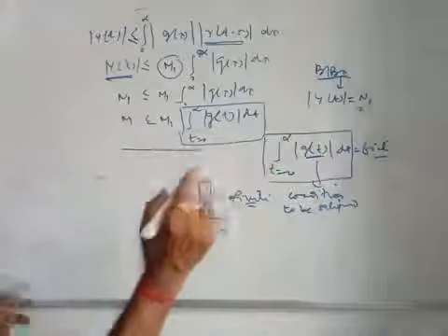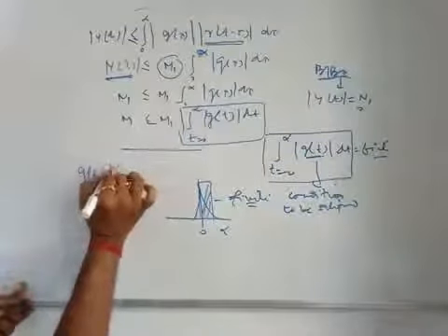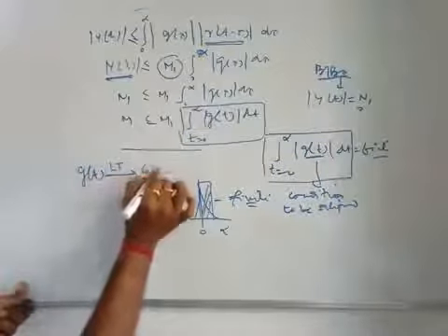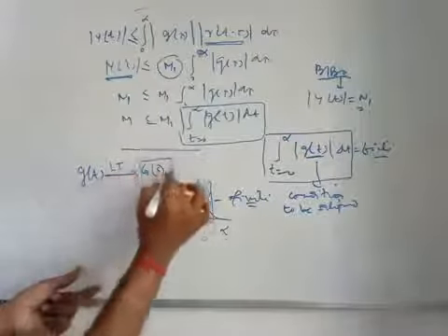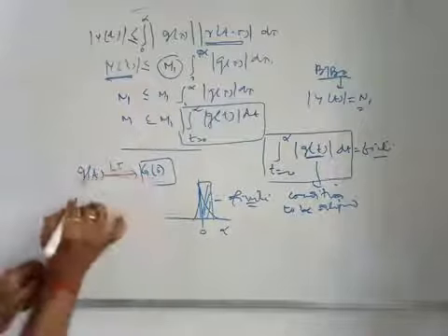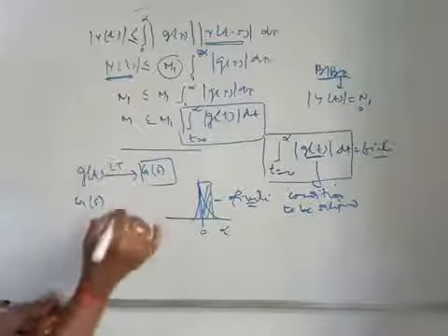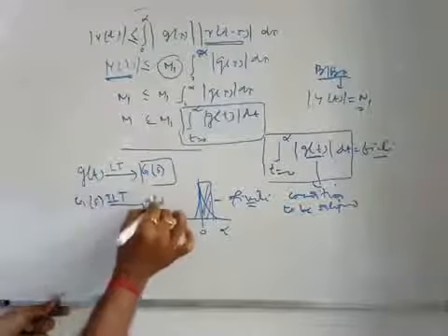And for the impulse response, say g(t), if you take the Laplace transform of g(t), you get G(s), right? So G(s) is your transfer function, as you know. If the transfer function is given to you, then from that you can get the inverse Laplace transform to get g(t).